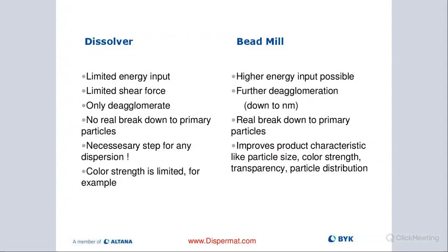We're homogenizing everything. It's really important that you do this properly and don't forgo it and go straight to a mill because you would have issues there with clogging of the screens or dynamic gap. So we really need to be sure that we are in a workable pigment particle size range before we start milling. And usually that threshold is about 10 microns.